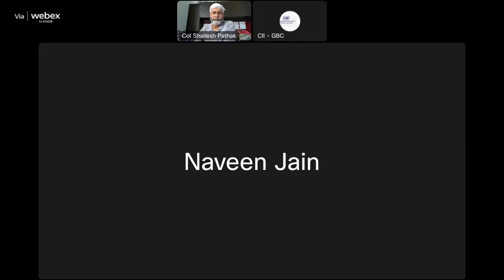As per the government, 100 kilowatt is kept as the minimum capacity for open access agreements. But commercially, projects are coming with 1.5 megawatt and 2 megawatt of connection sanction load. Only then are they coming with open access agreements. Below that, generally no one agrees.